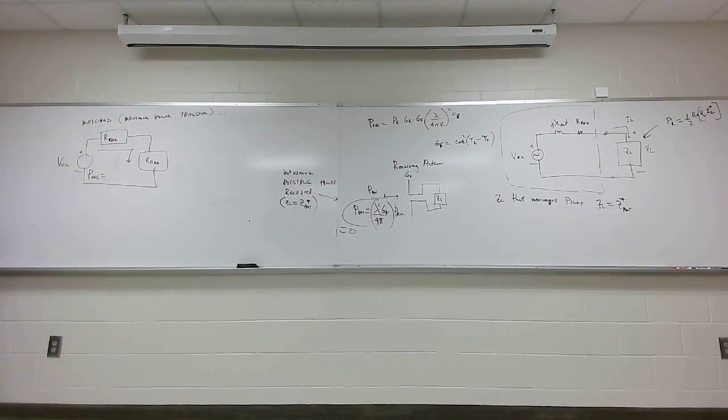And if you look at that, the total power received is equal to 1/2 V open circuit squared, divided by the radiation resistance, which is 2 R rad.